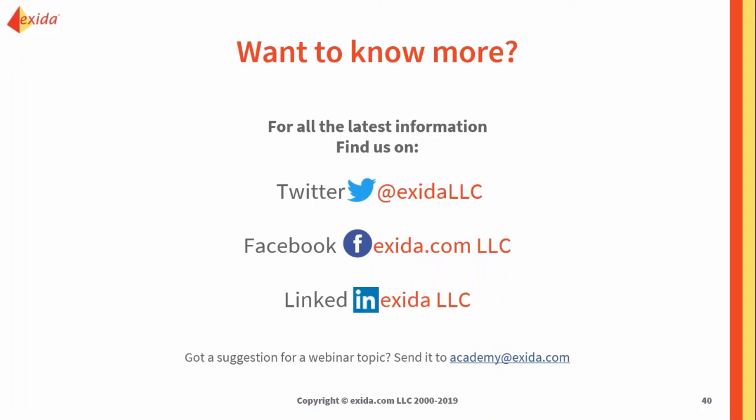What is the difference between a FIT and a mean time before failure? A FIT is going to be, once again, in those 10 to the negative 9 hours. It's going to be in that unit of measurement. FIT is very specific for that 10 to the negative 9. Mean time before failure can be in different units of measurement. It's more of looking at that time before a failure occurs, either safe or dangerously. So it can be looked at using those safe or dangerous failure rates as well.